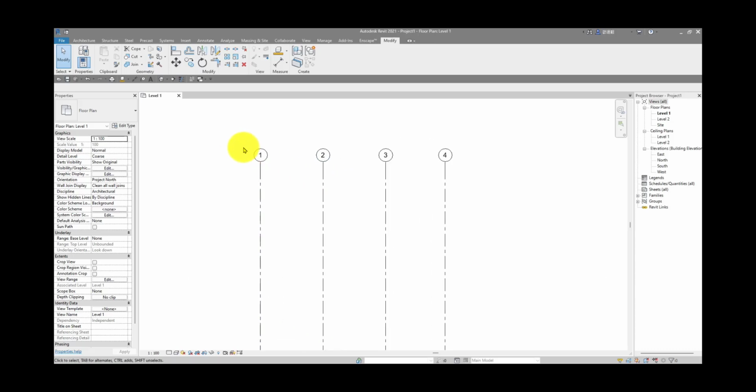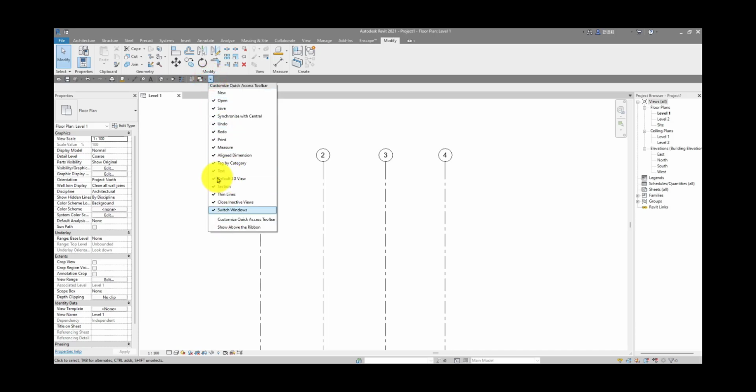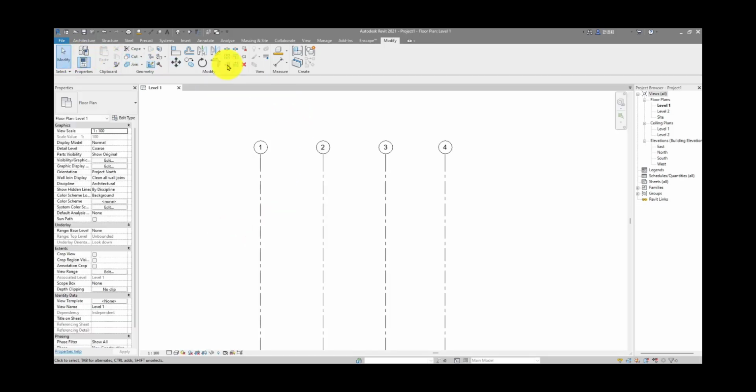Now, the only dimension tool in Revit. You see this dark ribbon right here in my view. Most of you are not going to have it below the ribbon; most of you are going to have it at the top. That's how Revit gives it to you by default. I just shifted mine down. You can move it by clicking on this arrow right here, and a pop-up menu appears where you can choose show above ribbon, and then it shows above that ribbon.